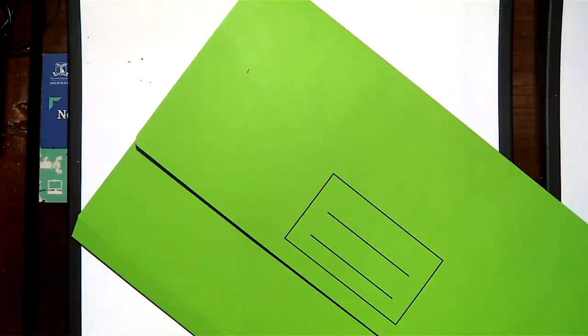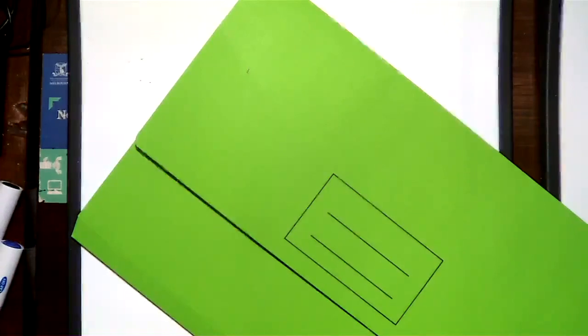Don't ask difficult questions. No, very simple for you. So when we draw the equivalent RC model like this, why don't we count the capacitance at the base? I mean, it should be a capacitance in parallel here, right? So, we don't count it at the base because the voltage doesn't change. Why? Because that one's tied to ground.